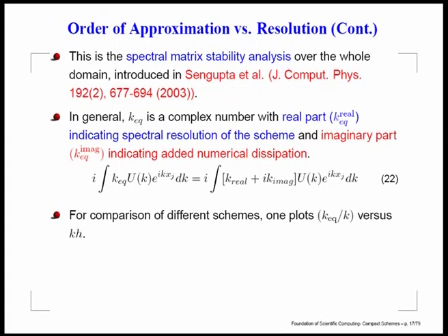See, that is why we have been discussing so far about central schemes. We do not want to needlessly bring in numerical dissipation, because chances are that will cause the solution to attenuate unphysically. So to avoid that, we are looking at central schemes.